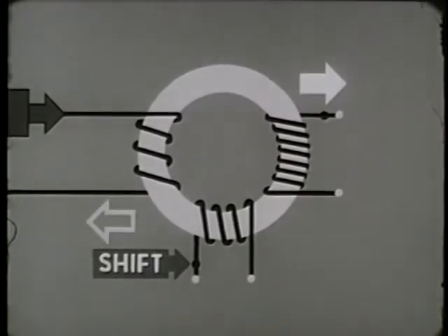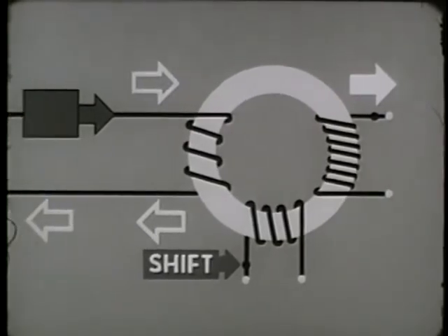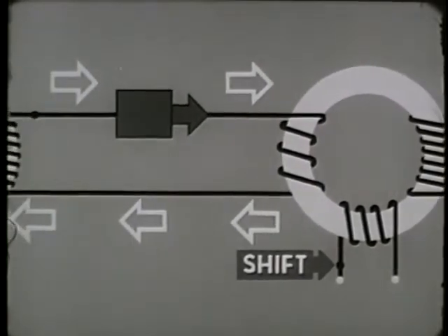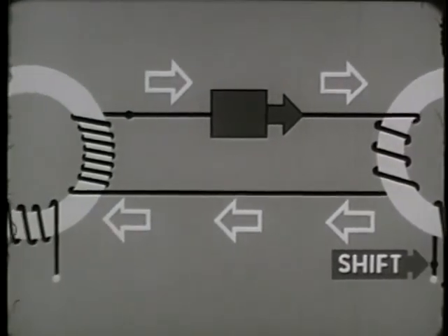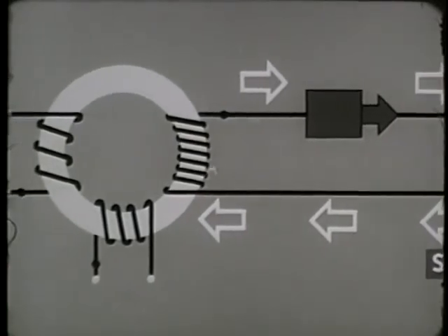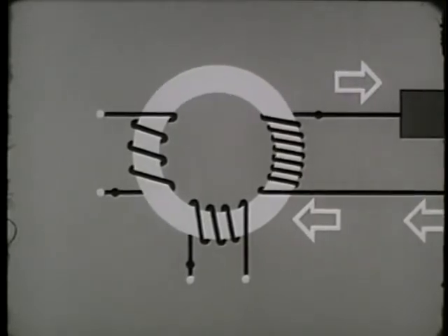Current will flow out of the dot side of the input back toward the first core. The one-way device won't stop it because it's going around the circuit in the direction it allows. This backward flow of information would, if unchecked, switch the first core, interfering with its operation.